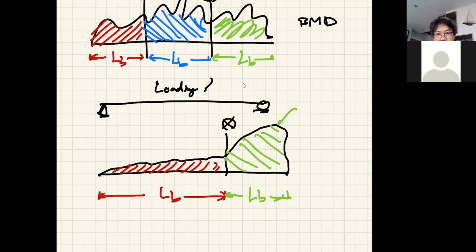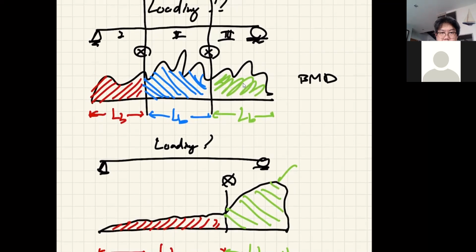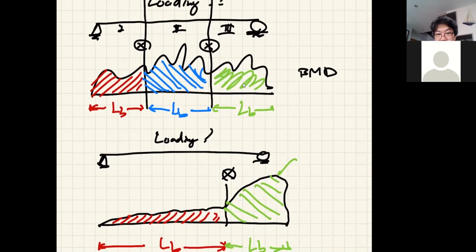Very good question. So we always have to investigate the unbraced length. And in one beam, let's say if you have 3 unbraced lengths, like the first case, you have to investigate all 3 of them before you can tell whether or not this beam is safe. And when you design the beam, again, the unbraced length will become the issue with the flexural capacity of the beam as well. So when you know the unbraced length, you need to use my table C or 4 to pick up the beam size.